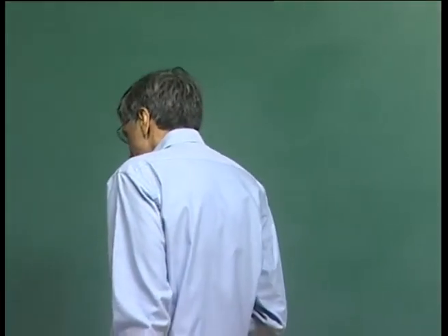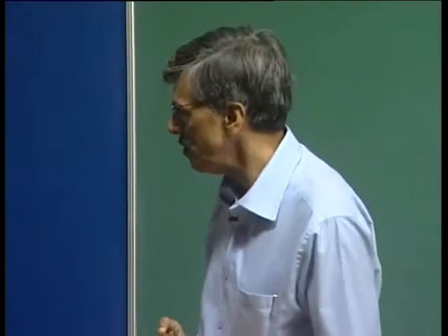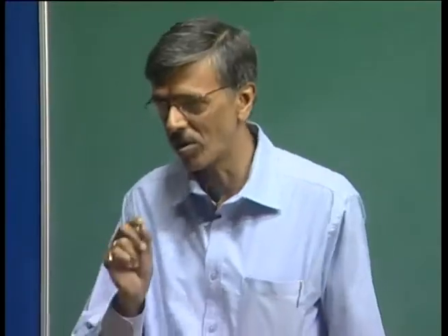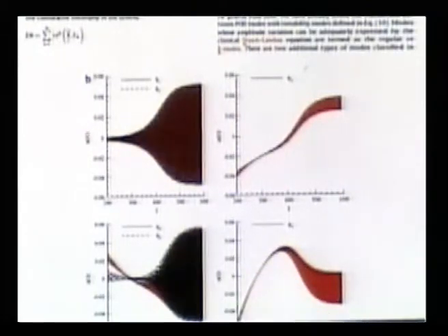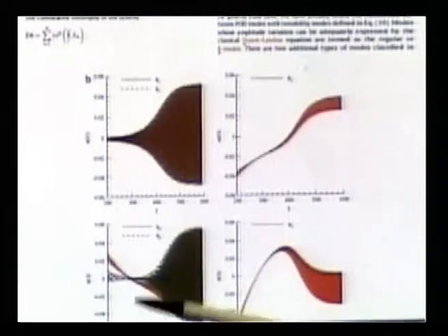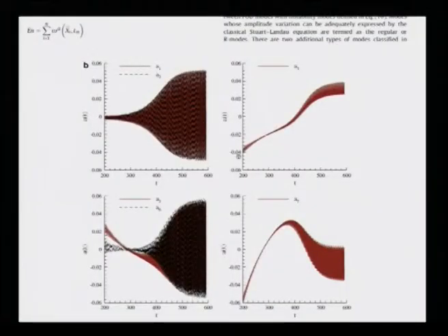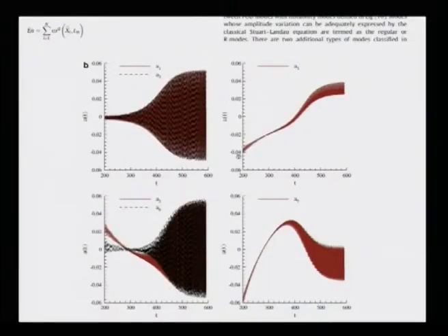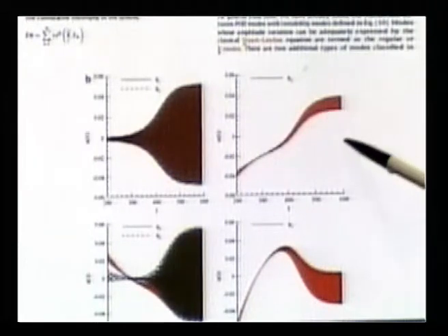Our aim is to take a very, very stochastic system and project it on a deterministic basis. And if we do that, then what would happen? If we are getting a perfectly deterministic basis, those have to be orthogonal. 1 and 2 seem to show that. But if you look at 5 and 6, to begin with, they are not orthogonally related, right. Despite that, as instability takes over and nonlinearity saturates, you do actually end up getting an orthogonal basis, right. So, in contrast, we have this shift mode, the anomalous mode of the first kind, the third and the 7th. That is what we are seeing here.